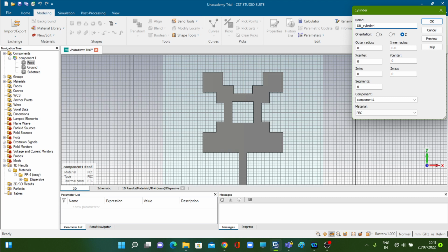Now this orientation basically means the perpendicular direction to the cylinder. This type of nomenclature we already have defined previously when we were defining the extrudes which we cut to generate the Hilbert profile. So likewise, this dielectric resonator will also have the same perpendicular direction, that is the z direction only. So we will select this z. Z is auto selected, so we will not change this selection.